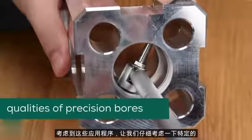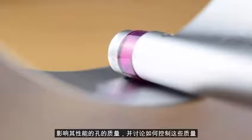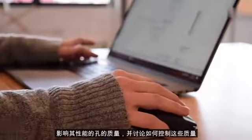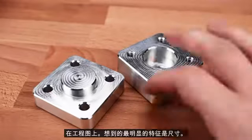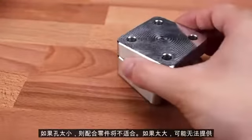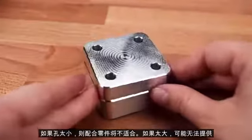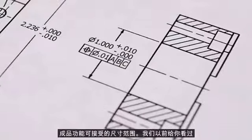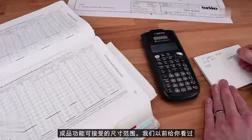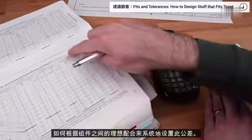With these applications in mind, let's think a little more carefully about the specific qualities of a bore that impact its performance and discuss how we might control these qualities on an engineering drawing. The most obvious characteristic that comes to mind is size. If a hole is too small, the mating part won't fit, and if it's too big, it might not provide the precision alignment that is required. The designer uses a tolerance to specify the range of sizes that is acceptable for the finished feature. We've shown you before how to systematically set this tolerance based on the desired fit between components.